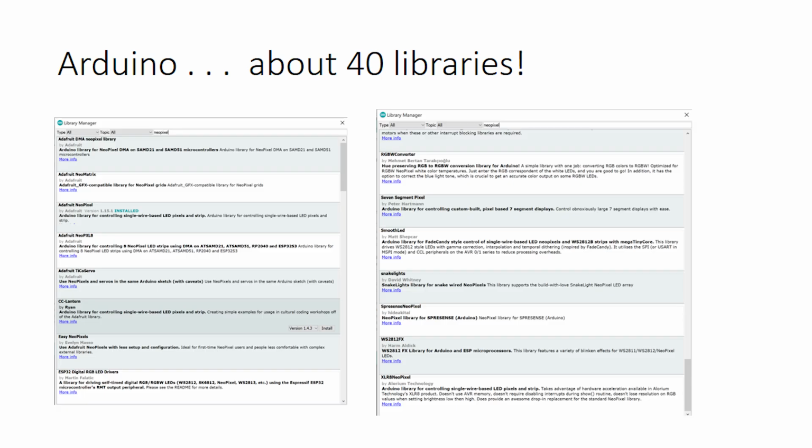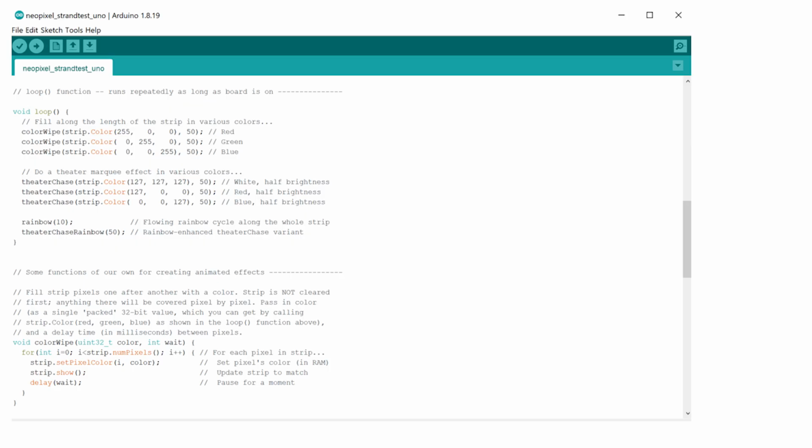You simply include the NeoPixel library, and then after that, there's what your code looks like. If you take the time to go and look at Davy's presentation on the 2812 boards, then you'll see he's got the same sort of code in there. It's very, very simple. Once you've included the library, you use words like colour wipe, theatre chase, rainbow for 10 milliseconds. The commands are very, very simple, and it's suck it and see. You can just try this stuff in a REPL loop. Try it, see what happens, change it, see what happens.